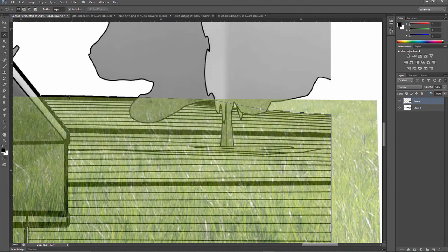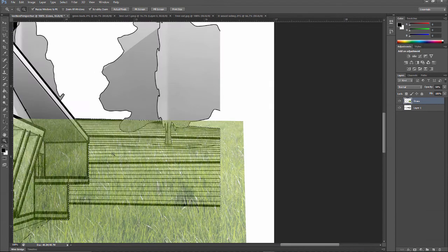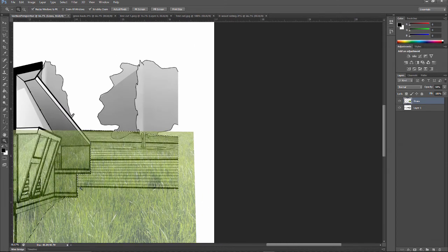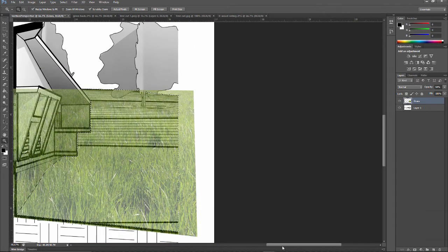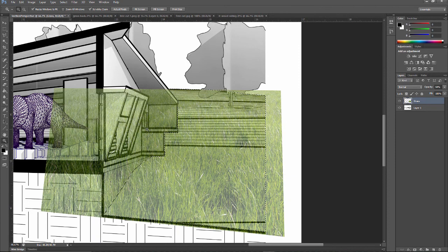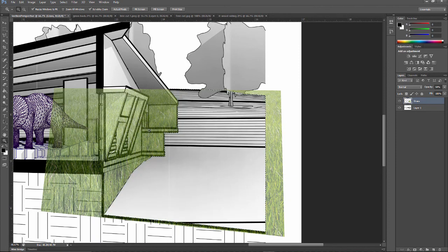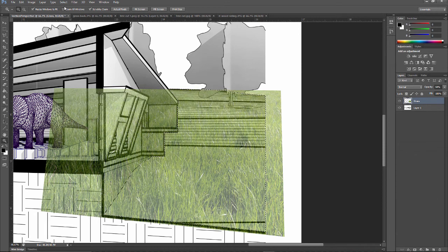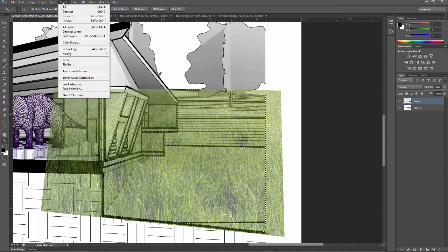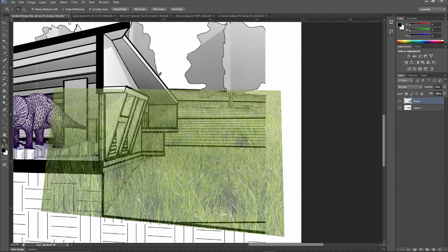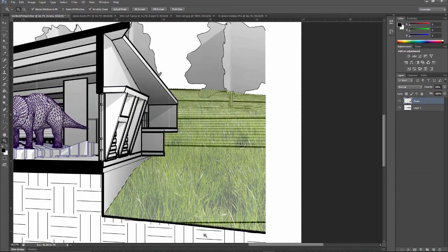It's kind of like a really quick version of an undo while you're building what can sometimes be a really fairly complicated selection inside of Photoshop. So that done, I actually don't want to delete this interior portion right here. So if I hit the delete button, that's going to get rid of the inside and keep the outside. So let's undo that. What I actually need to do is invert my selection, select inverse, delete, and that's going to crop that portion out.